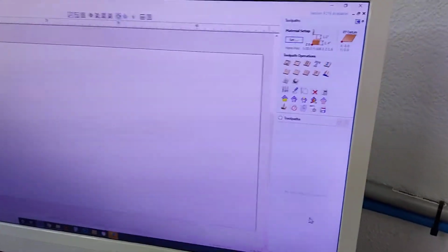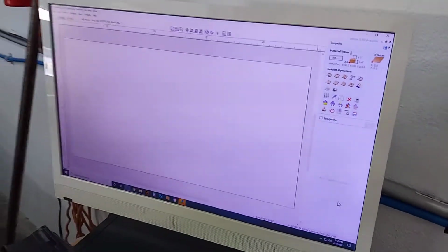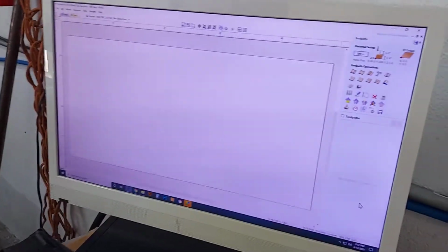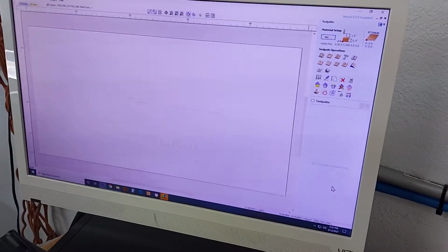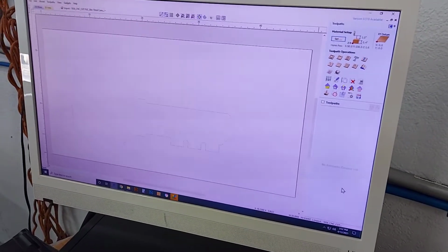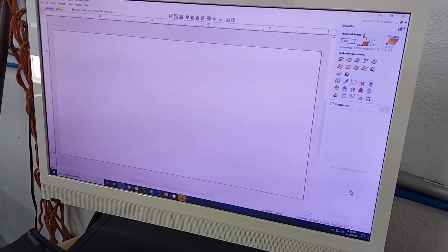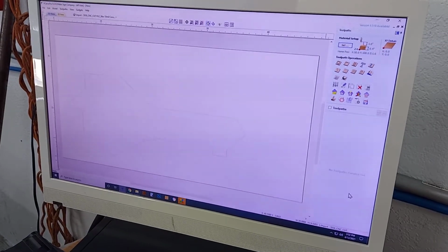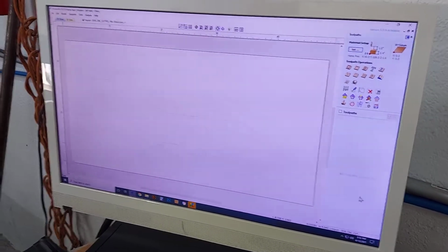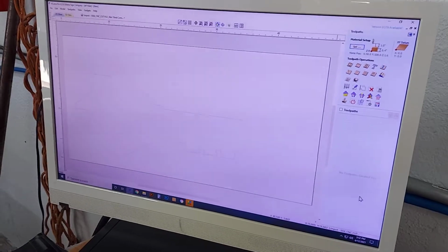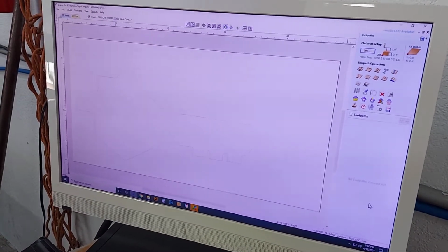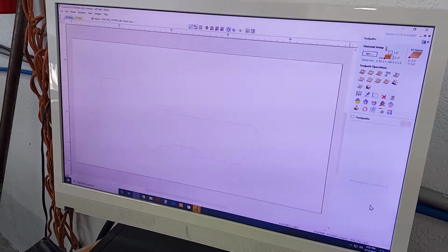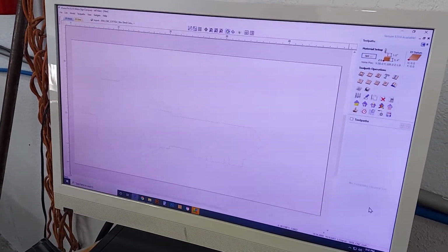Now, I'm cutting 10 mil coroplast. I happen to know, now if you're a new user, you may not know what tooling, what feeds, what speeds, etc. That's part of the education, it's part of knowledge. But for the time being, I happen to know that 10 mil coroplast cuts fairly nicely with what's called a 1/8 inch O flute. So it's a single flute upcut. The speed is going to be about 18,000 RPM. The feed is going to be about 85 inches per minute.